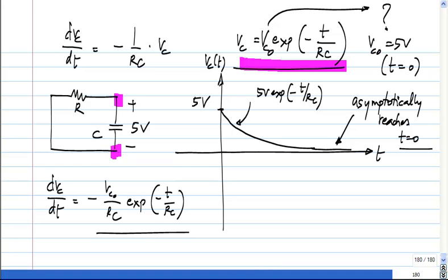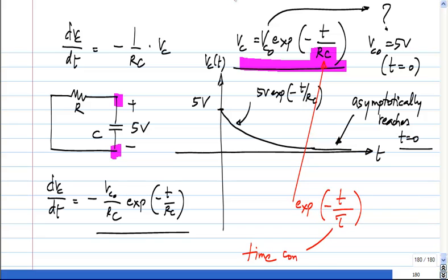And this quantity RC here, like we will see later that we will do more calculations of this circuit, and that thing appears all over the place. Okay. So, this exponential will have minus t by some quantity that has dimensions of time. Okay. So, this is known as the time constant. Okay. And that comes about because when you write the homogeneous differential equation like this, the coefficient is over there. Okay, you have minus 1 by RC. That is what makes this RC go into this exponential, right? So, that is a characteristic of the solution to this differential equation. That is the time constant. And it is very common to hear the terms like RC time constant of a circuit. So, this is what it is.